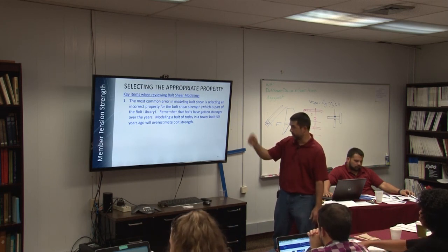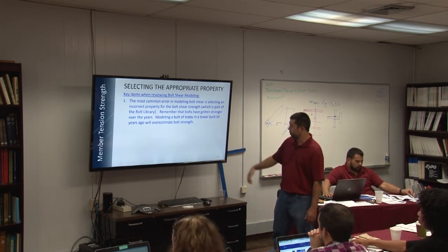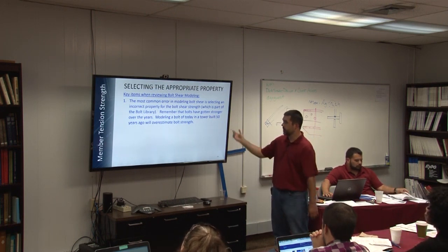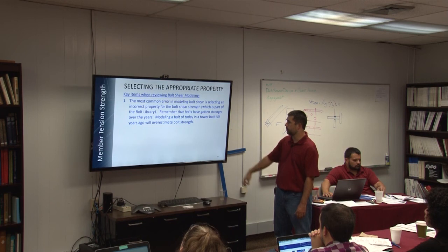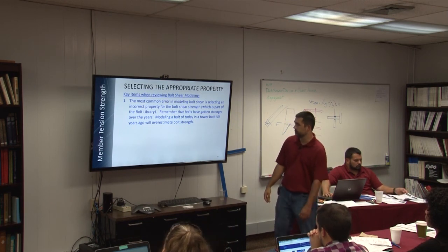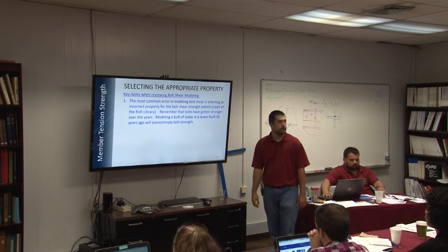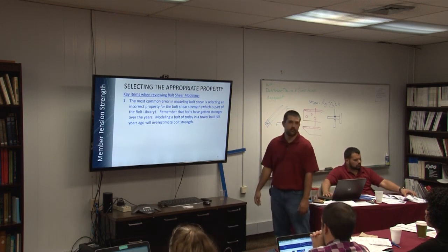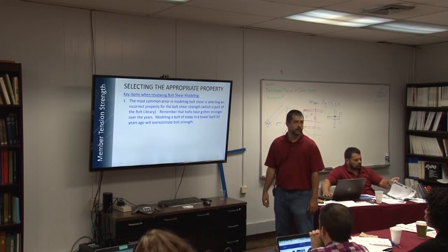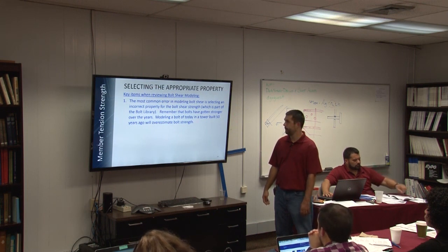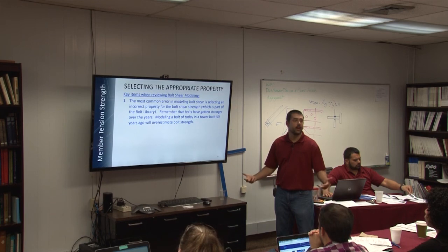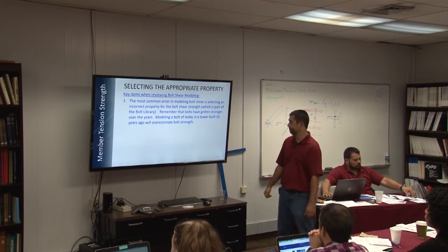I'm just gonna... this is just beating you over the head. Most common error in modeling bolt shear is the bolt shear strength. Bolts have gotten stronger over the years. Modeling a bolt of today in a tower built 50 years ago will overestimate shear capacity. So be highly aware of that. That's always a comment that we have when we peer review, is bolt strengths don't seem to be appropriate. And the general mistake is to make them too strong, so you're not identifying problems.